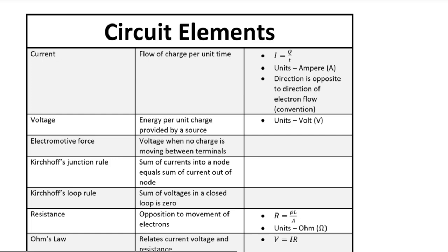This is because the wire itself has some resistance associated with it and will therefore take away energy from the circuit. Two different rules associated with what happens with current and voltage in a circuit were then introduced. The first rule, known as Kirchhoff's loop rule or voltage law, tells us that the sum of voltages around a loop must be equal to zero. The potential difference created by the battery must be equivalent to the sum of the voltage drops across each component in a circuit. This was in a sense described as conservation of energy for a circuit.